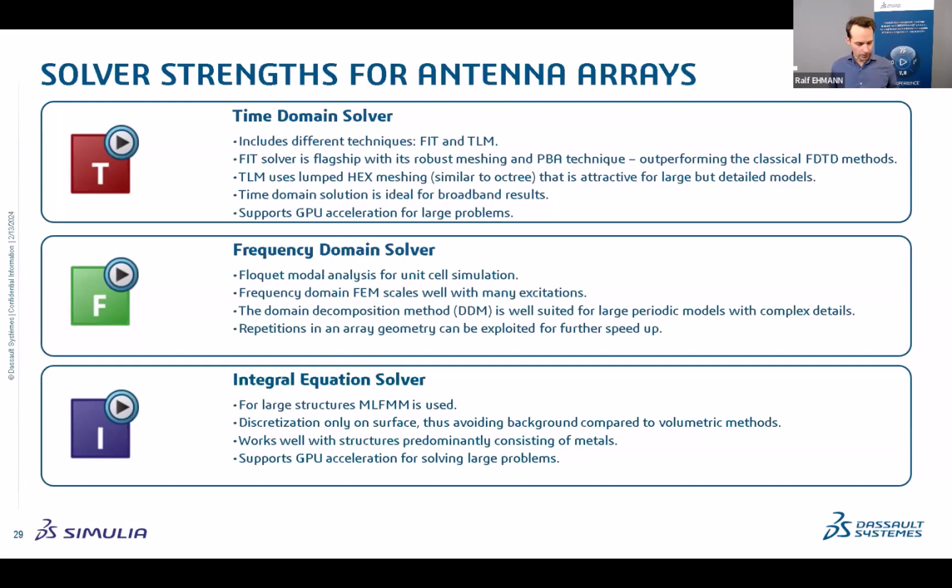Then there's also the integral equation solver, of course, for large structures, which would be using MLFMM. It discretizes basically only the surface, so of course avoiding a lot of elements in the volume or in the background, and it works well for structures that are predominantly metals, although of course it supports dielectrics as well, and also for acceleration GPU can be used.